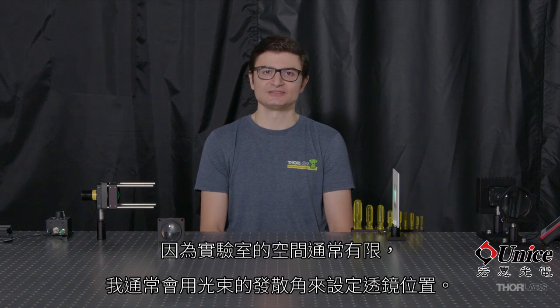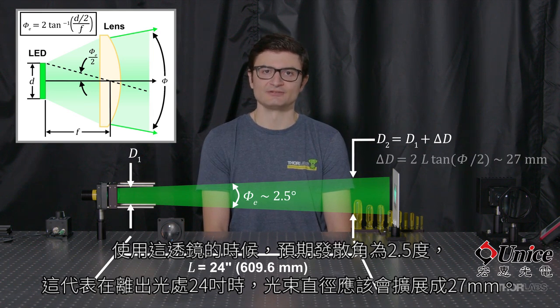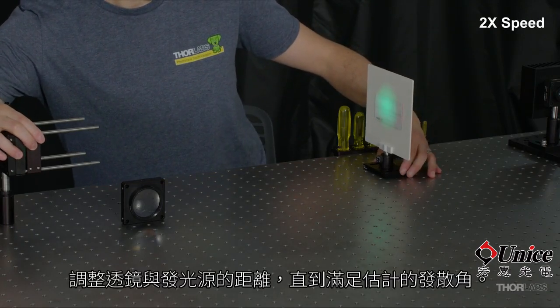Since space in the lab is usually limited, I like to use the divergence of the beam to set the lens position. Using this lens, we expect a divergence of about 2.5 degrees, which means the beam diameter should expand by about 27 millimeters when measured 24 inches away from the output. I'll adjust the distance between the lens and the emitter until this divergence estimate is satisfied.